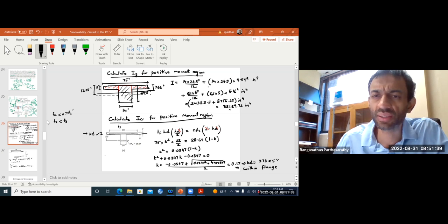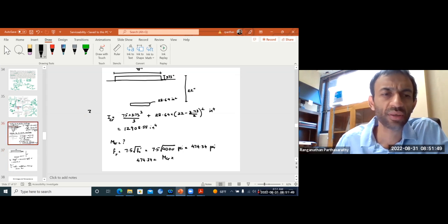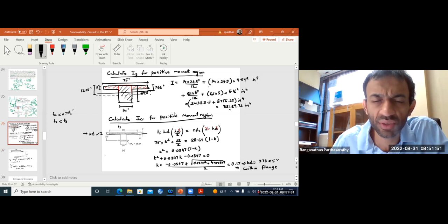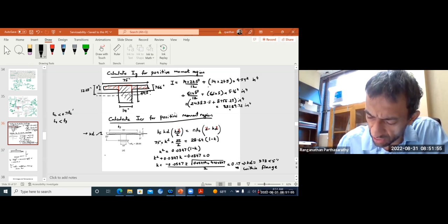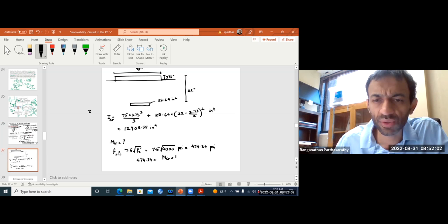So your 474.34 is your cracking moment times the distance of the neutral axis, 24.5 minus 7.66, 16.84. So times 16.84 divided by